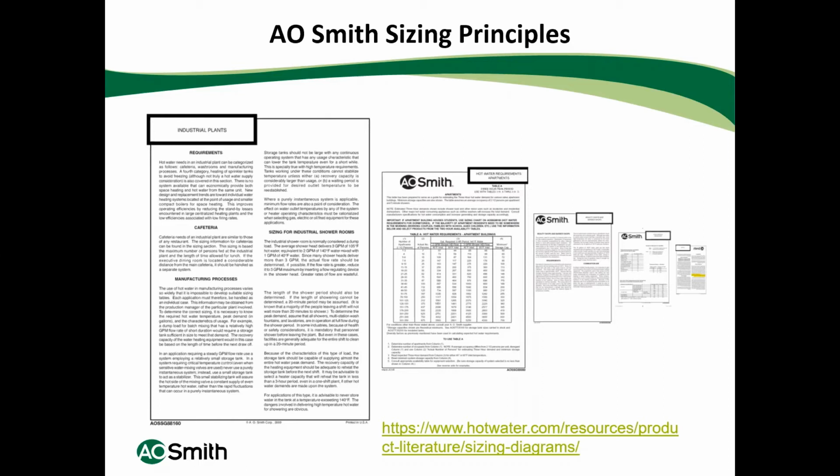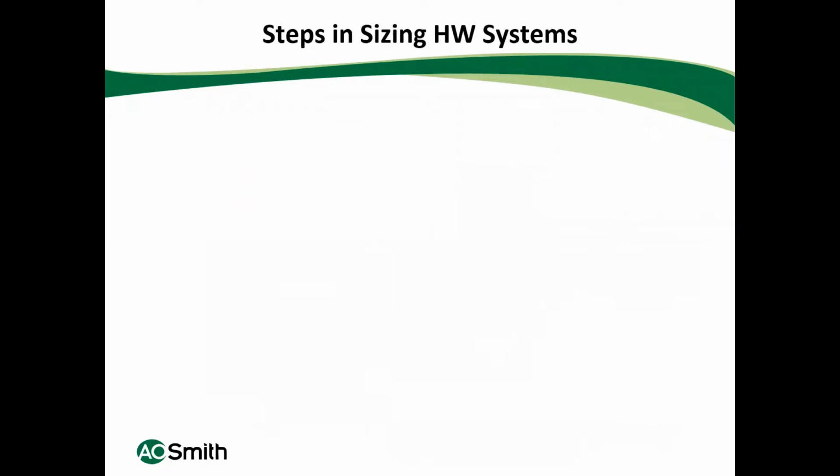Then we have documents for apartments, hair salons, concrete, several churches, schools, all that is available in that sizing section there. Basically, when we help with sizing, we need to determine the type of building. An apartment building is categorized into 3 different types, and you'll see that on ProSize: a low peak, medium peak, and high peak demand type building.